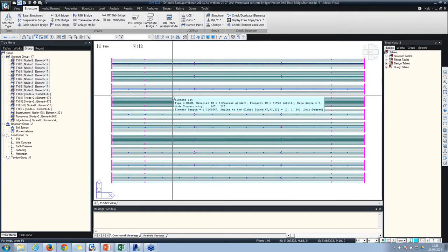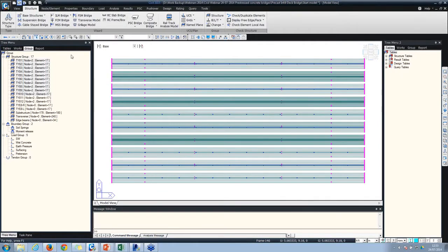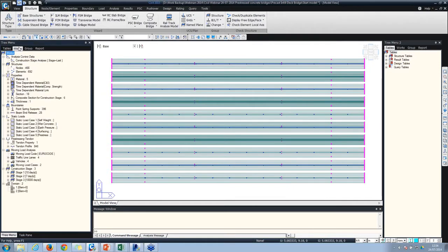So you can quickly create tendon profiles by just defining the type of section you are going to use in the model, and then quickly generating the profiles, debonding them, and deflecting them, or changing the shape of the tendon itself. Then the next step is to define reinforcement. Because the software can do the design of the sections, you can input reinforcement for both slab and for girder. So it will do a complete composite section check considering reinforcement and the pre-stressed tendons.